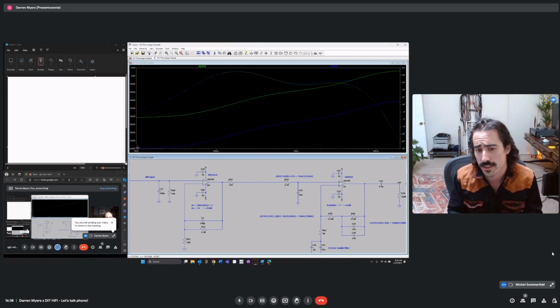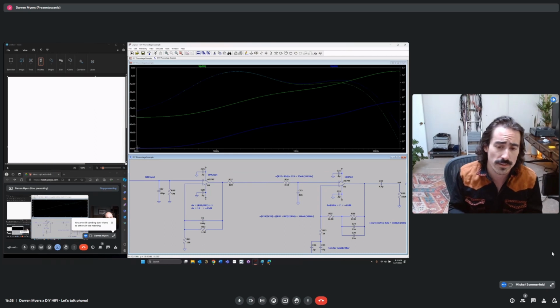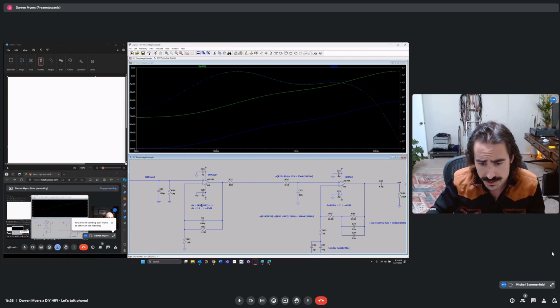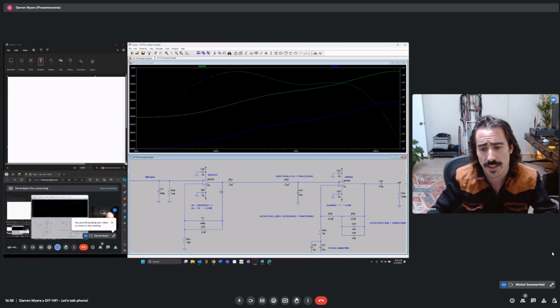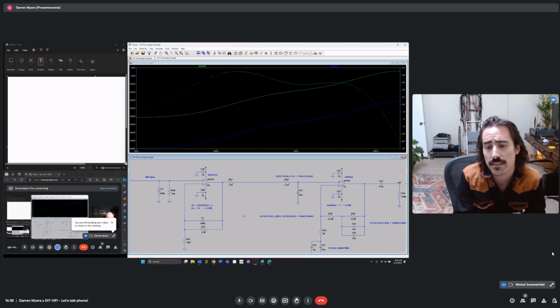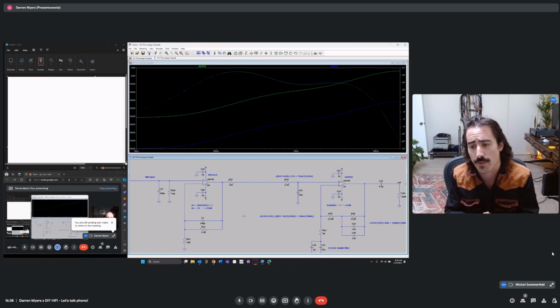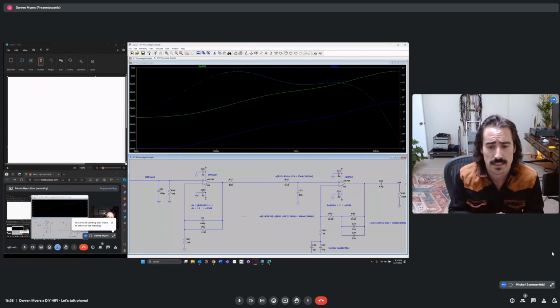So it would cause an issue with the overload specification of the phono stage, which we will discuss after we circle back here. So that's why we're only applying so much. It's this middle ground where we're getting the best of signal and noise, and we're also getting the best of the overload, which is really a compromise in the end.